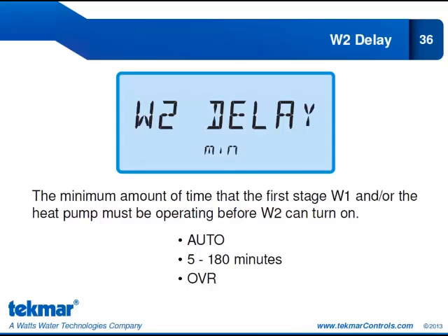This W2 delay is not applied when the heat pump is locked out. It's not applied when W2 is the only stage available for heating. And it's not applied if the heat pump is turned off in respect of the balance point. So it won't hold off W2 in cases where we need W2.